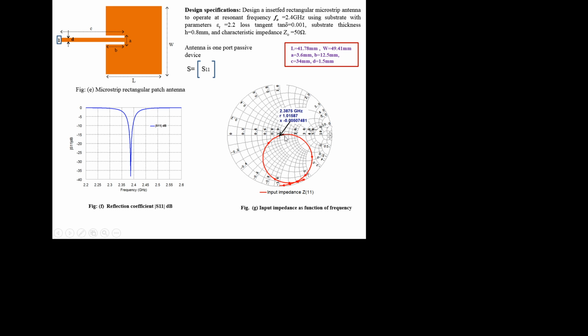So this is the frequency variation. If you move like this, the frequency changes, and for all those frequencies the impedance changes, R and X values change. We can observe that by moving this marker, the impedance varies as you move over different frequencies. Only at the resonant frequency R takes the value 1 and X is approximately 0. So that is a matched one.